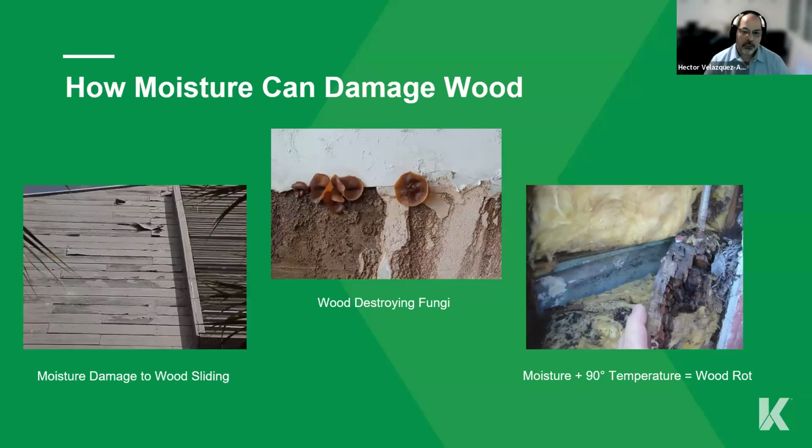because they're cracked, because they lost section enough. If you clean them two or three times already, mechanically clean, you're causing problems to that pipe because now it's too thin and it starts to break apart, which causes water intrusion into a unit. And sometimes people will say, well, it's not even close to a window. Yeah, but where is your drain stack close to that leak? Sometimes it even comes from the fire suppression system that is leaking, and you don't know until you see the black mark on your ceiling or on your wall.